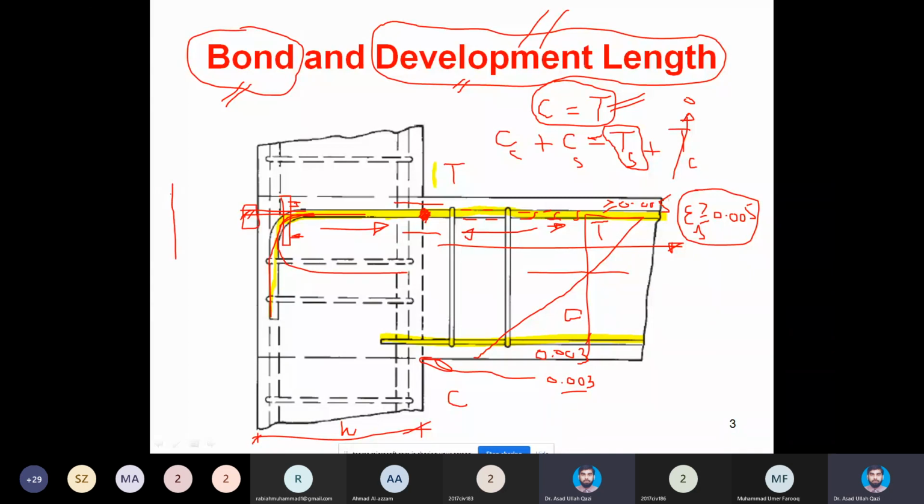Imagine that you have a cross section. In that cross section, you put a conduit, and in that conduit, you loosely place the steel bar. And then you start expecting that C will be developed by the concrete and T will be developed by the steel. Sadly, you are mistaken, because this T can't be developed unless you have a bond between steel and concrete. So either you put grouts and try to bond the bar with the concrete, removing the conduit, or otherwise use some epoxies to grip the bar with the concrete.